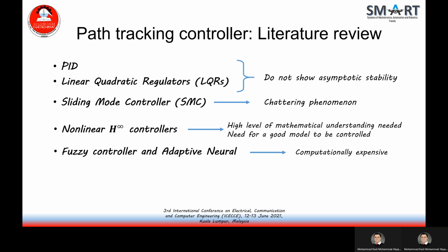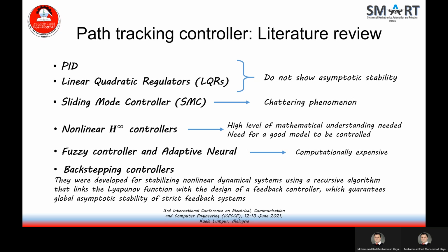In tracking a ground target, a vision-based fuzzy controller for a quadcopter is found in the literature, where the fuzzy control doesn't require an accurate model. For the same purpose, a direct adaptive neural controller was designed to control the translational motion of the quadrotor. However, such controllers are computationally expensive, which might lead to system instability. On the other hand, backstepping controllers offer an alternative.